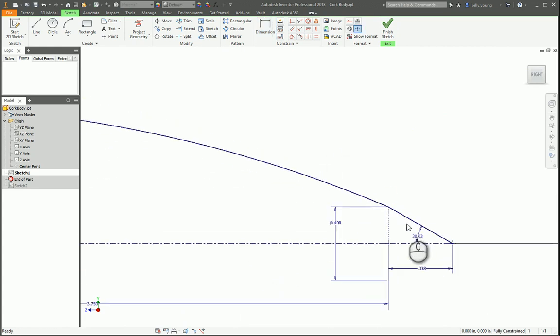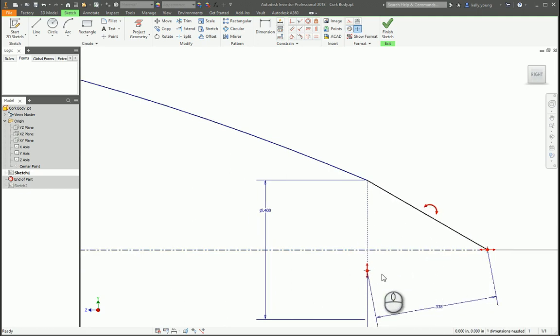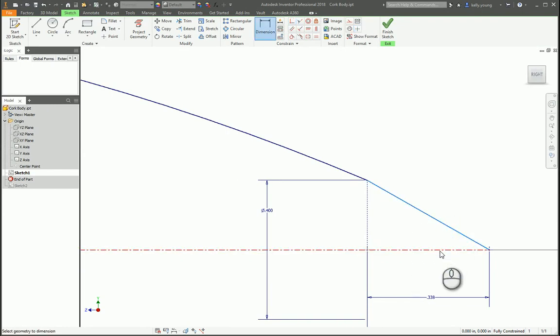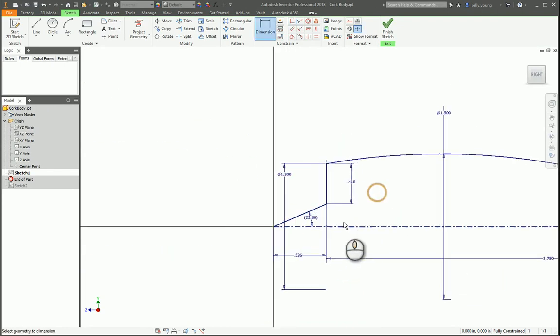So I'm assuming that this is the same thing. If you delete this, now this one has degrees of freedom, so now you know your points can go. So if we actually put that point on this line, we don't even need this dimension, now it's going to be a reference. Same thing with over here, now we get a reference dimension.